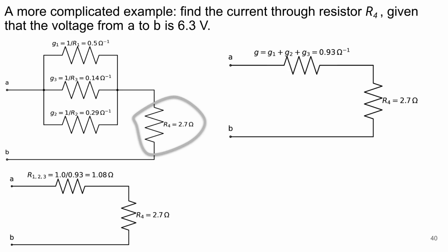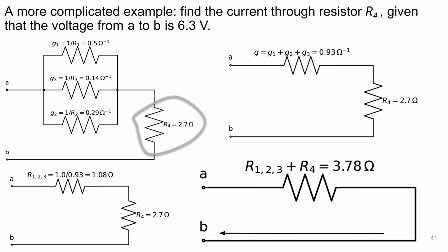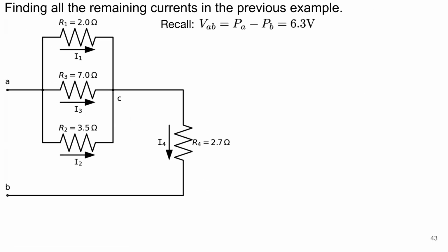We now have 2 resistors connected in series. We combine them into one, using the results of video 1 on constant currents. The desired current entering terminal B in the reference direction shown is the same as it would be for the original schematic. Therefore, it is the current that flows through resistor 4. We find this current, denoted here by I4, using Ohm's law. It equals 1.67 amperes.